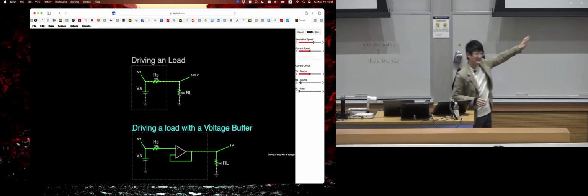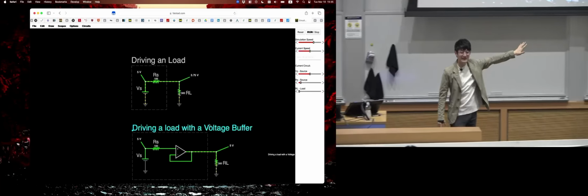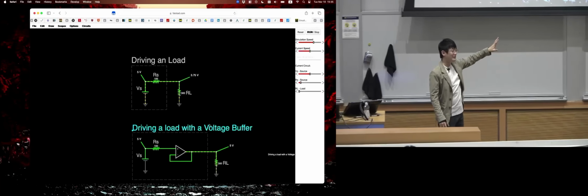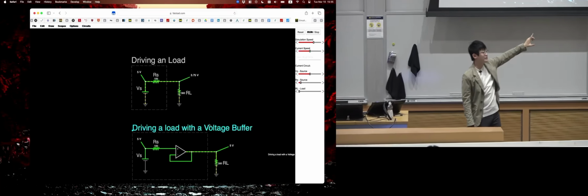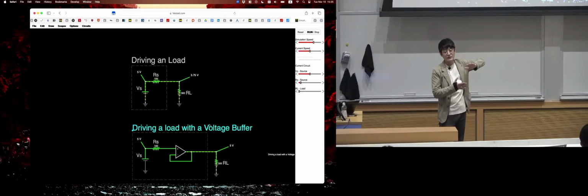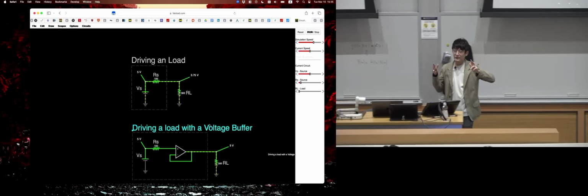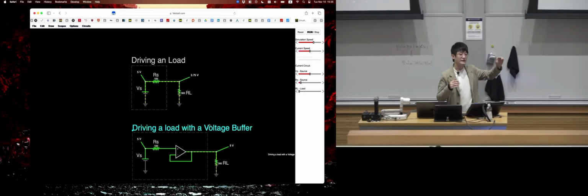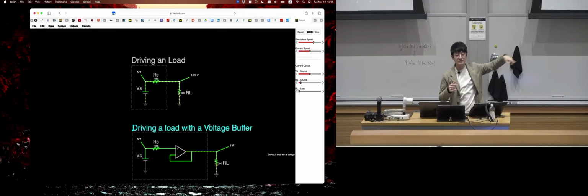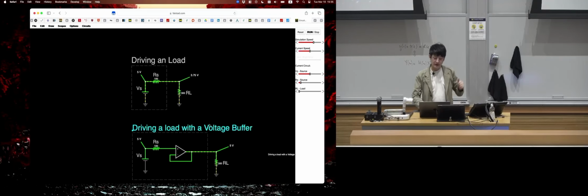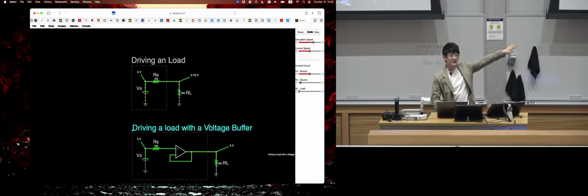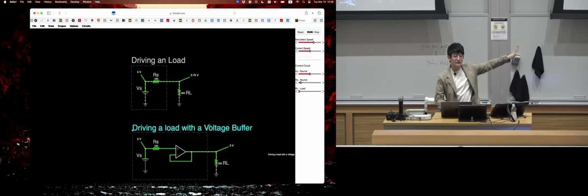Obviously, this is a super ideal situation because this circuit is simulated. But in real life, within the operating range of this op amp, you should be able to have a relatively consistent output from the other side of the op amp as a voltage follower. So always check the data sheet. But these things are typically handled internally for you.